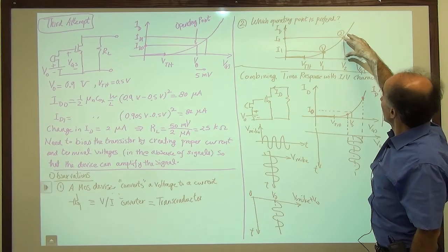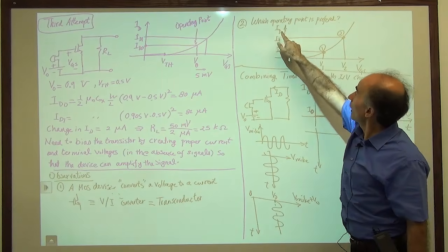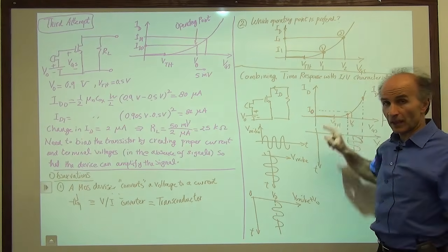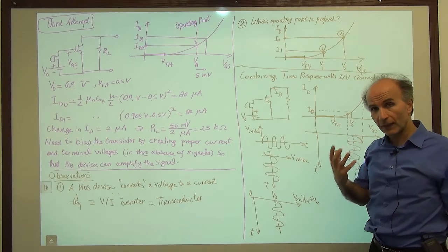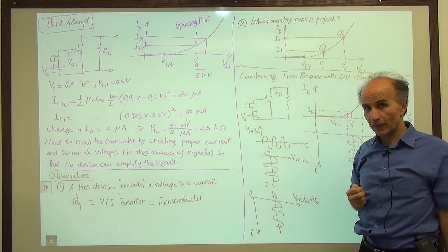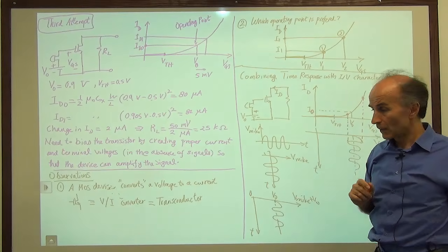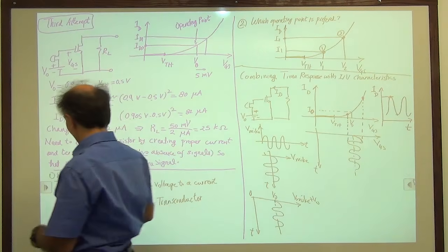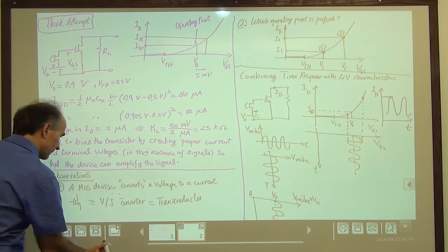Okay, so what we are thinking is maybe you can call the slope of ID versus VGS something, and use that to feel how strong the transistor is as far as voltage to current conversion is concerned. So we do that. We exactly define that. So let me go to the next page.